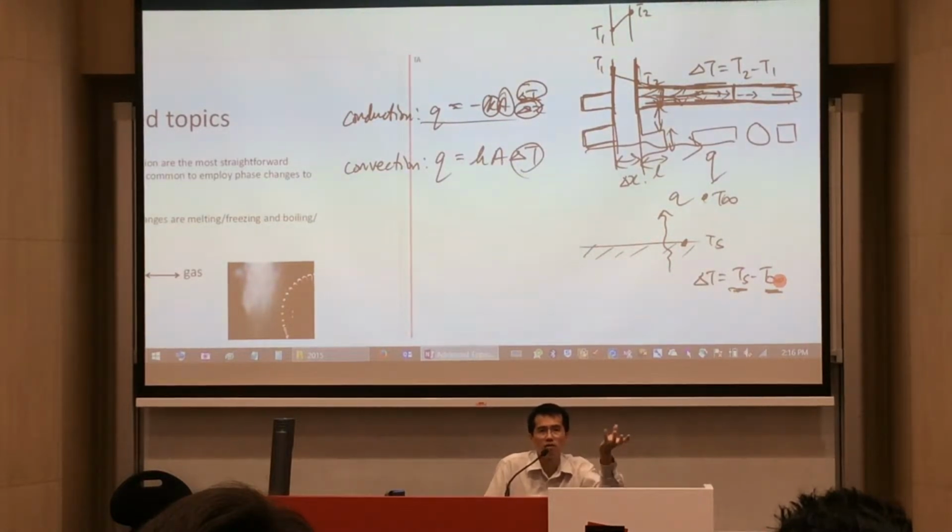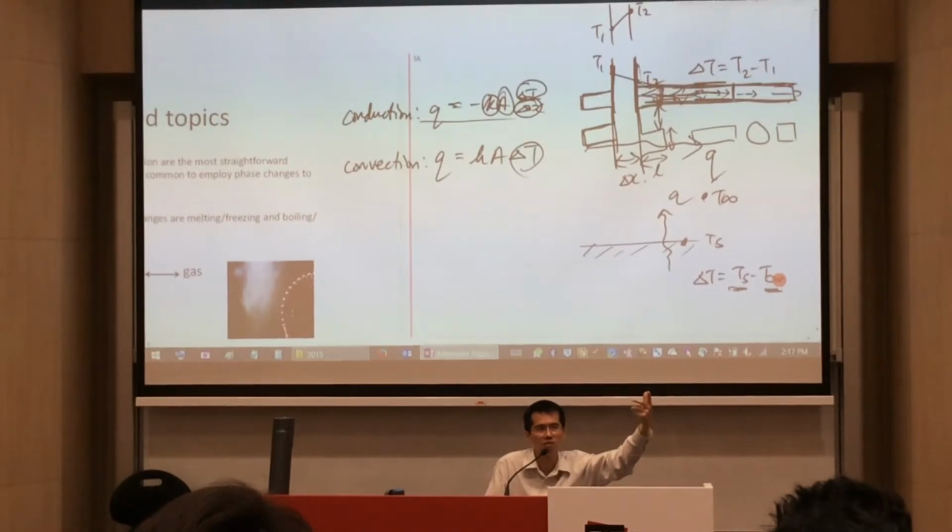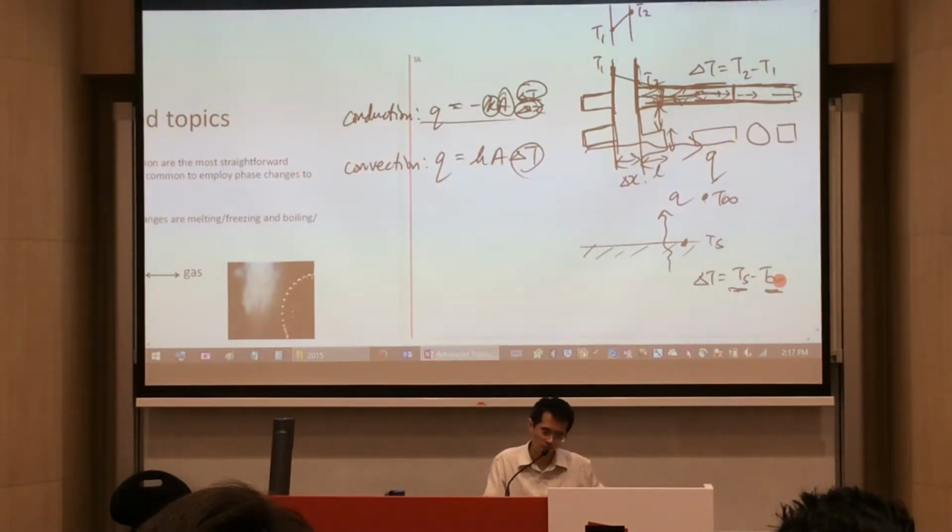Yeah, you can make it hotter so as to encourage more heat to transfer over, but usually you start with that object at a certain heat that you want to cool down. It doesn't make sense to heat it up further just to increase heat transfer. So your delta T faces the same problem as the delta T in conduction, that you can't really do much to it.